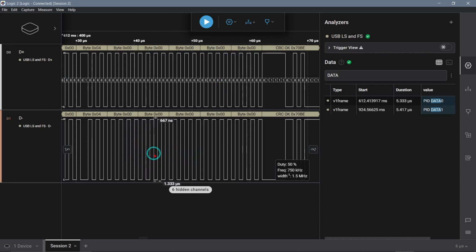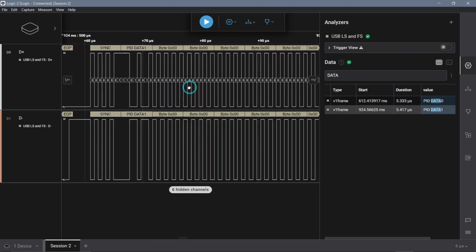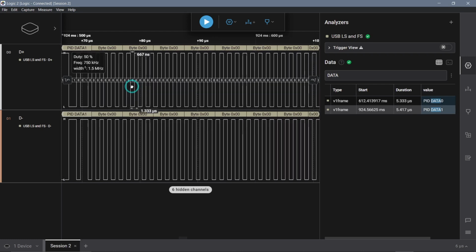So you've got a 6-key rollover. You can hit up to 6 keys at the same time in one report. If you hit more than 6 keys or some strange keyboard combinations, you tend to get a value of 0, 1, which is some sort of error, and it's a nondescript code. In any case, byte 4, as I said, we know that to be the scan code for the A key, and so that's what I hit. I hit A, and that was data 0, and if you go to data 1, it is now saying, okay, basically the A key is up.